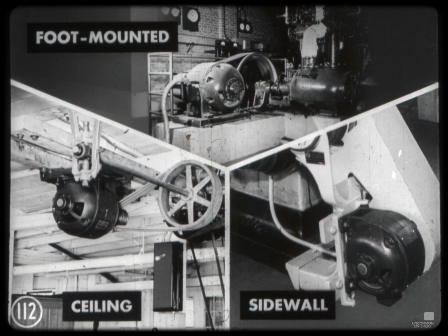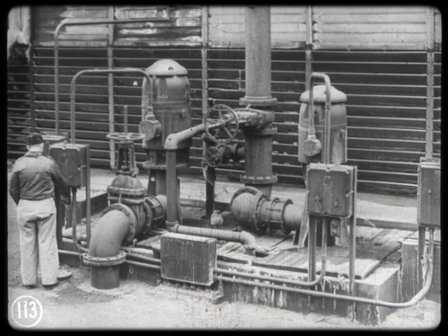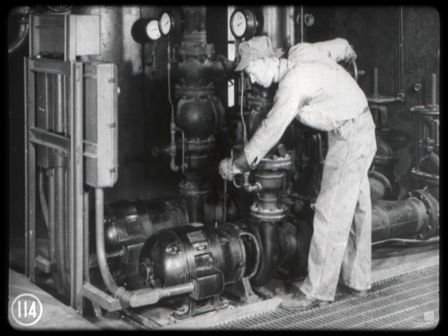The motor mounting must always be considered, too, and for most jobs, the foot-mounted type is entirely adequate. By rotating the end shields, this same motor can be mounted on either the ceiling or sidewall. Where a machine has a vertical shaft, as this cooling pump does, then a vertical motor mounting is used. Quite often, machinery manufacturers make use of face-mounted or flange-mounted motors for mounting the machine directly on the motor or mounting the motor on the machine.